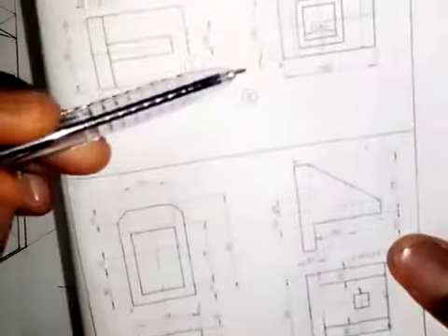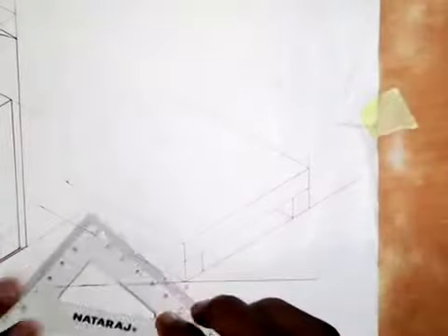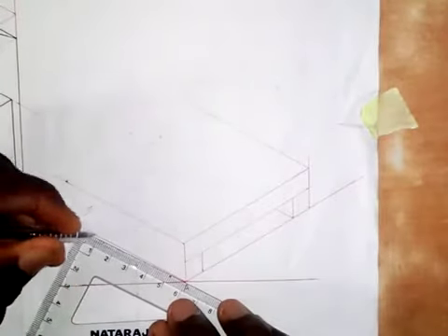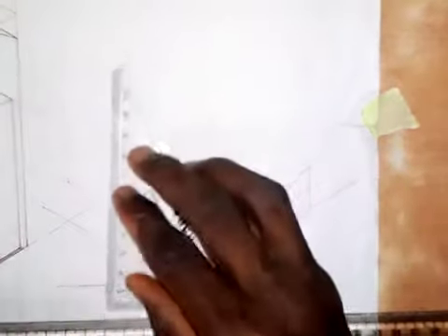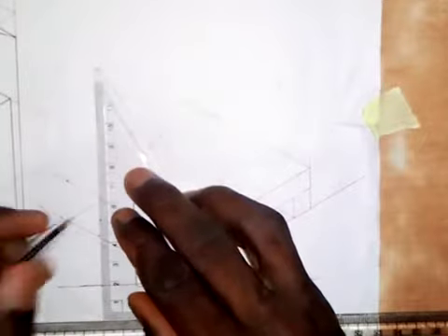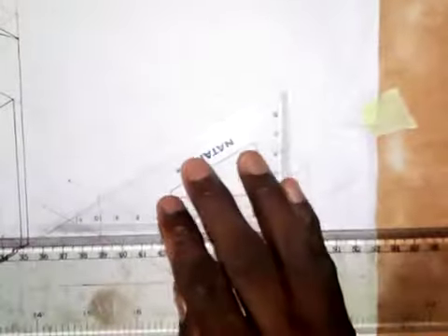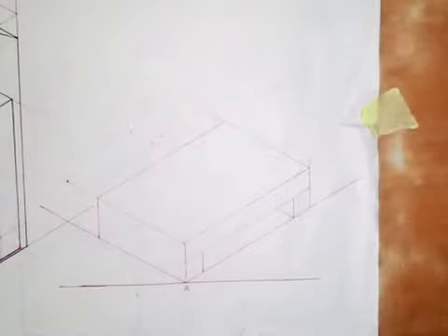Okay, so as we have that, the width from here to here is 100. So I will take 50 instead of 100. As I said that I'm drawing outside of this object, so I will take 50 millimeters. So this is 50 millimeters here. So here I will draw a vertical line. This is a vertical line. Then I will transfer this to the other side like this. Okay, so this is how the base is going to look.